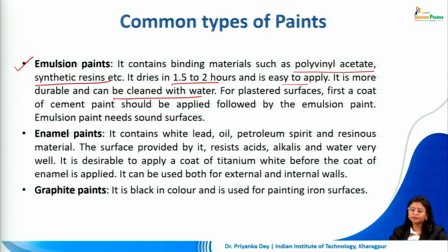For plastered surfaces, first a coat of cement paint should be applied, followed by the final finished surface of emulsion paint. Emulsion paint needs sound surfaces.